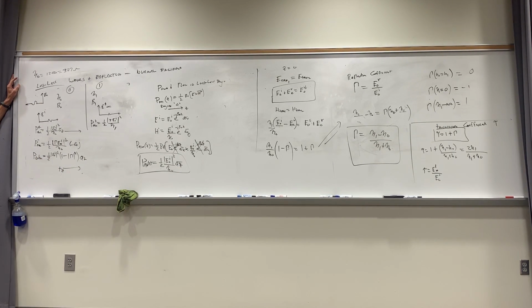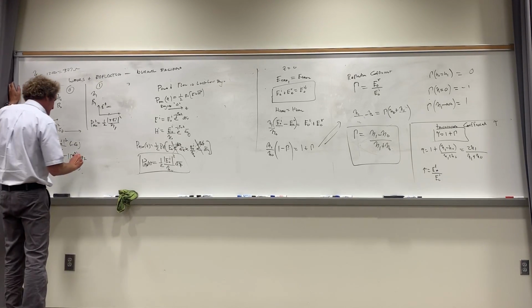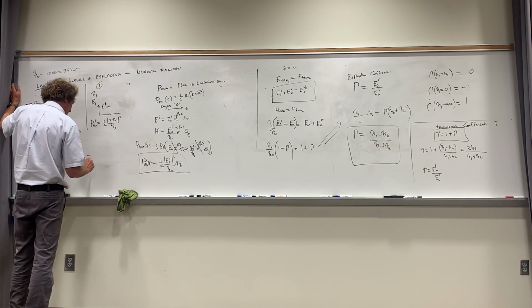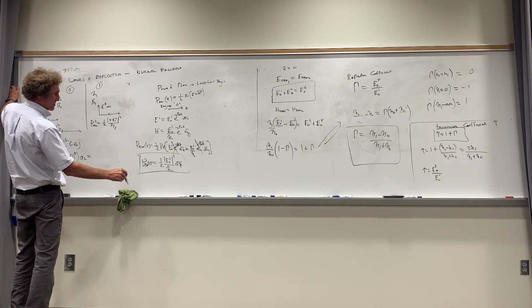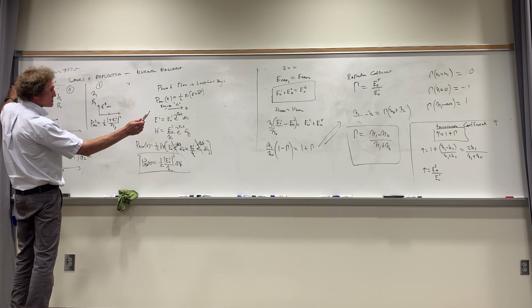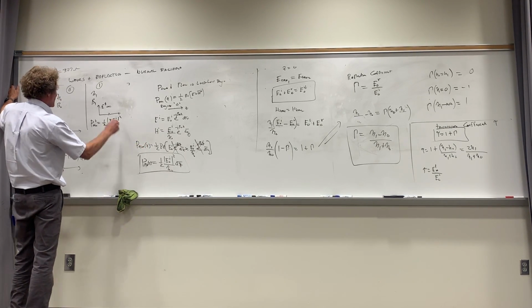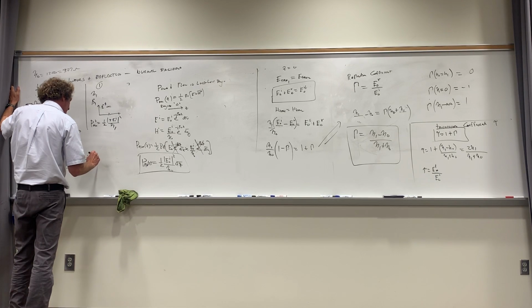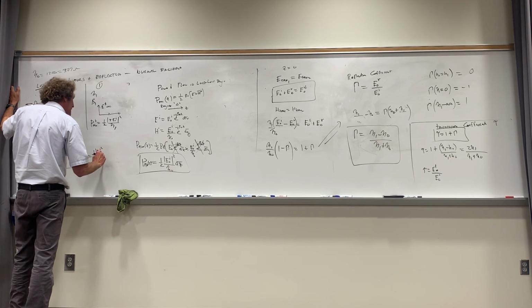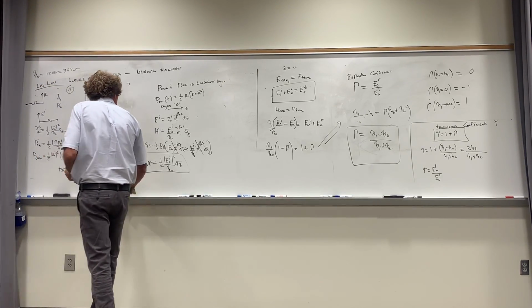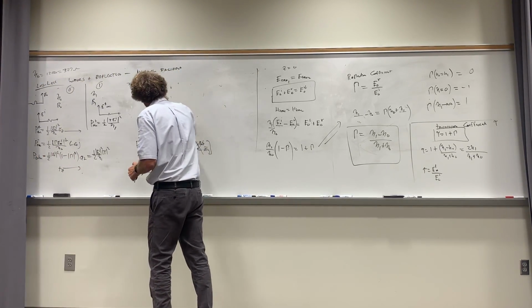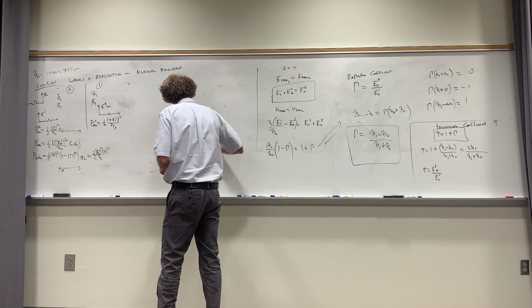Do you all see that, class? With me? Well, that has to be equal to the total amount of power that is transmitted, and this, in fact, is equal to PAV. It's equal to 1/2 times E naught incident squared over eta 1 times the magnitude of tau squared. Now please watch this next part. It's important. And this only is good for normal incidence.